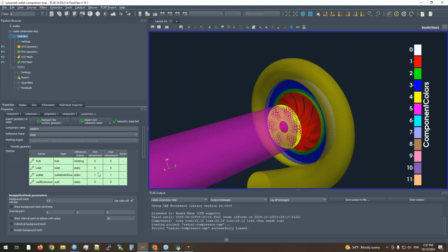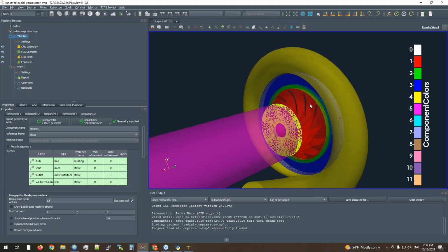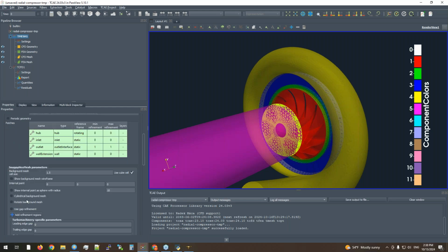You can set different minimum and maximum level, and the maximum level is typically imposed for highly curved areas. If the internal engine decides that the curvature is higher than some thresholds, then it applies a higher level of refinement. In this case, everywhere will be level 1.